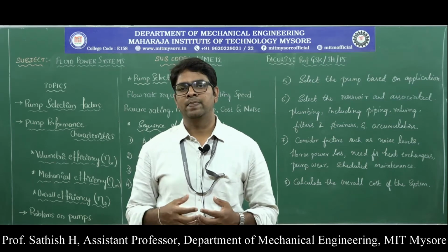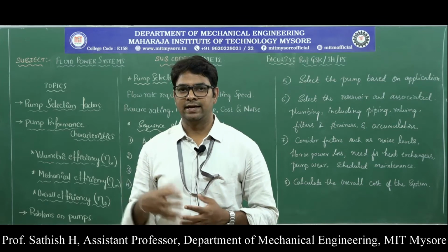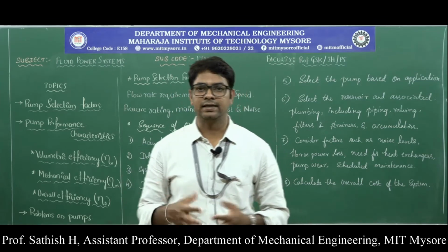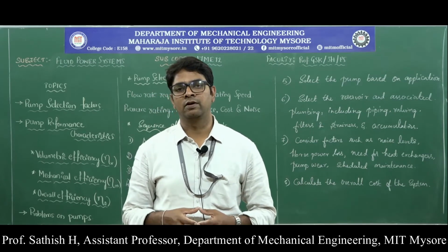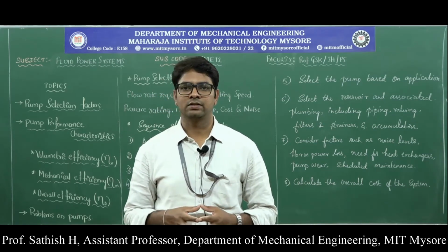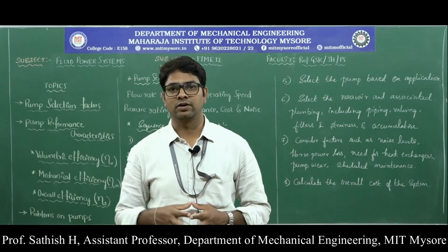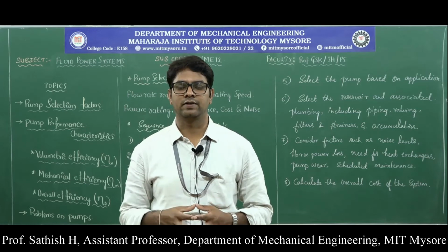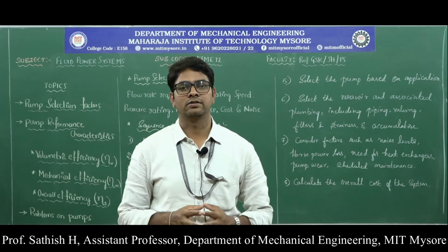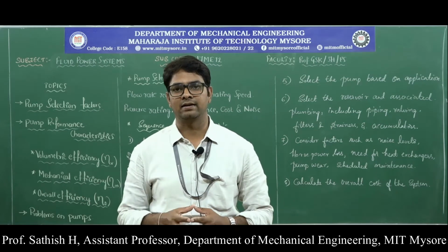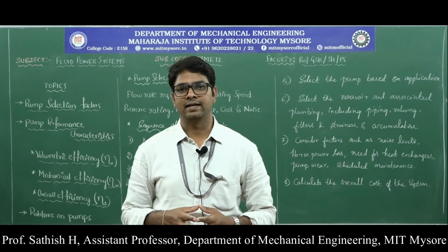Similarly, the mechanical efficiency accounts for the power losses or energy losses inside the pump other than the leakage. What could be the other reasons? It could be because of the wear of the moving parts, or some of the other components like bearings. There are losses of energy in the bearings as well. So other than the leakage, any losses will be categorized into the mechanical energy losses, which we can find out using the mechanical efficiency.